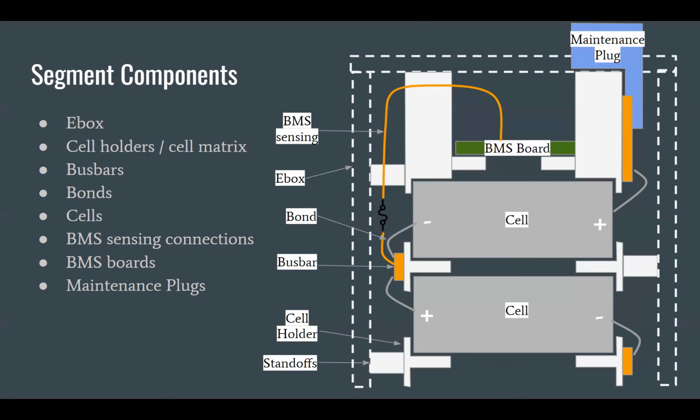For the box, luckily for most forms of plastic, there are special, I don't want to say epoxies, but special adhesives that actually melt the base material and can adhere it more effectively. With something like super glue or epoxy, you're basically just putting glue in between. You're not really doing anything. But for both polycarbonate and CPVC, you can buy a special goop that will actually melt the material and make it one piece of plastic. So that's the plan: we'll have someone go through and make a seam on both sides and then scoop it out to make sure that we don't have any fillets or anything.